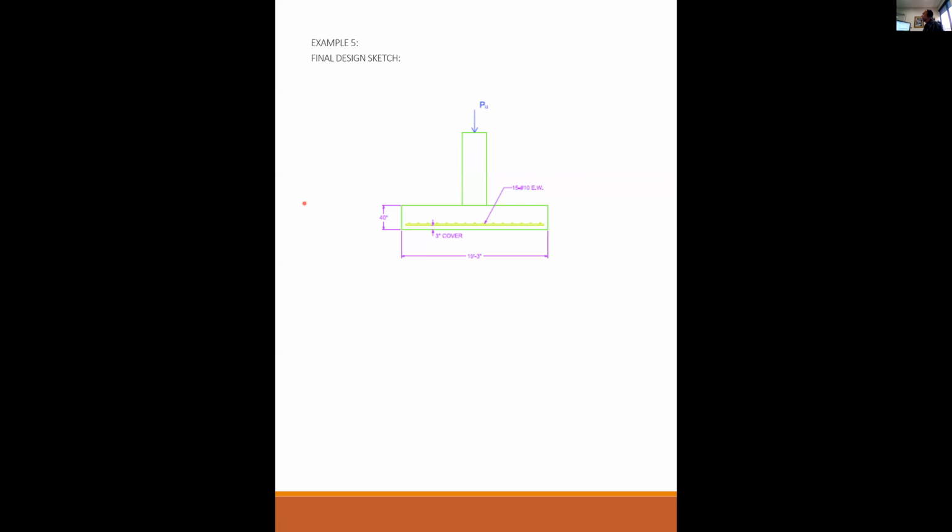All of that is done by the contractor responsible for the grading and what's the word I'm looking for? But anyway, the preparation of the soil. Once the soil has been prepared, then you bring in another contractor with a backhoe. He digs out this square shape wherever these columns exist. Once this shape has been dug out of the ground, this is a hole in the ground.